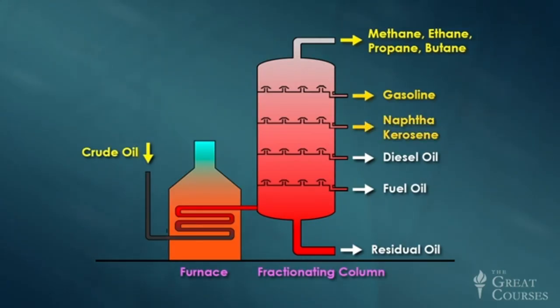Farther down below are naphtha and kerosene. And at the very bottom is a heavy residual oil. With further processing, lubricating oil is extracted from this residual, and some of what's left can be used for asphalt and as fuel for oil-fired power plants. The remainder is sent to a facility called a coking plant, which cooks the sludge until there's nothing left but carbon.